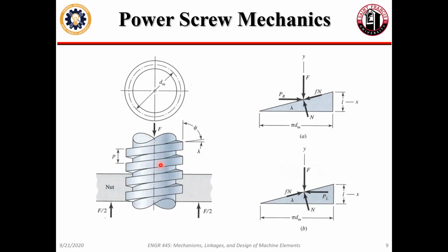So when I'm thinking about how to put this screw in, I'm going to need a bearing for the screw to ride on or for my handle to ride on. But I'm also going to need something to take up that thrust load too. Could be a thrust washer, essentially just a nicely oiled washer sitting between the rest of your material and some shoulder or collar on the screw, something that doesn't move and the screw is just riding with.